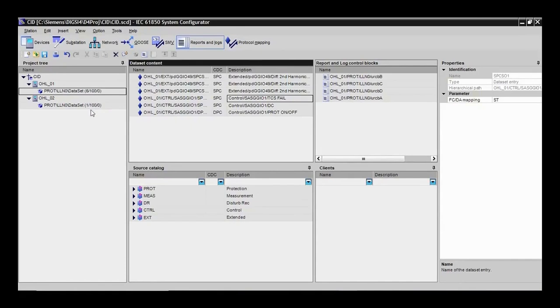Here, something very important appears, which is what it tells you. It tells you there is an advantage, even though in the theoretical videos I told you that it is preferable to use the standardized logical node. What does this mean? However, it is preferable at your station to use the generic signal. Why? Because it tells you that if you come to your matrix and put, for example, 20, 30 generic signals and connect them to logic inputs and a lot of other things, the generic signals are present here in the dataset, and you can copy-paste them regardless of how their programming looks.